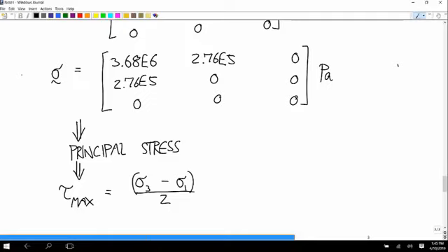Max? Yep. You just plug that into your eigenvalue calculation. It gives you your three principal stresses. For triangle rule? Oh, for this? Yeah, right. I don't know what it is, but there is. But how much easier could it be than plugging that into your calculator and calling the eigenvalue function?